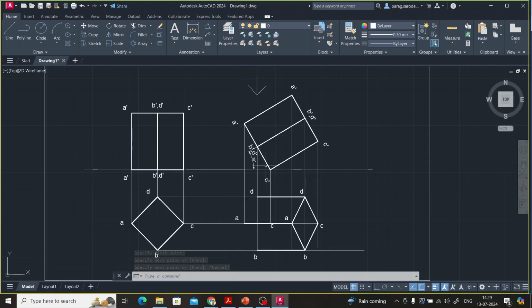Okay, now for joining this bottom, what do we need to do? Join the outer faces. As here ABCD is connected in order. Here first we will join the outer faces. The outer faces, that is the outline of the figure, is always a visible line. So AD is the outer face or outline, so it needs to be drawn with a thick line, just like this. AD is the outer line, AB is also an outline of the figure.